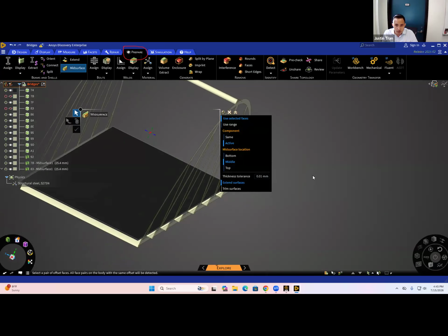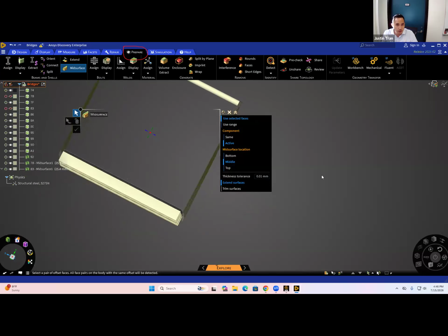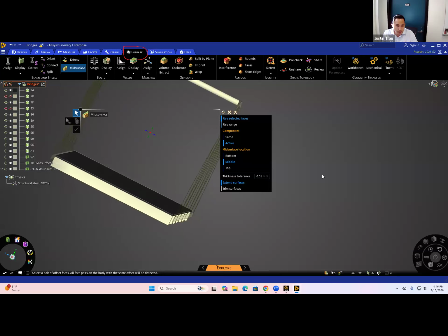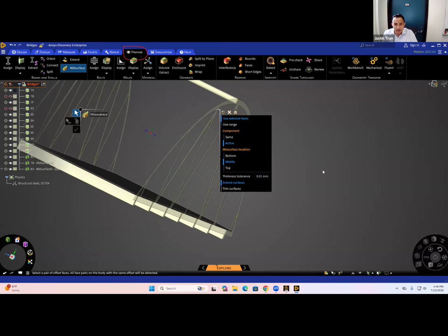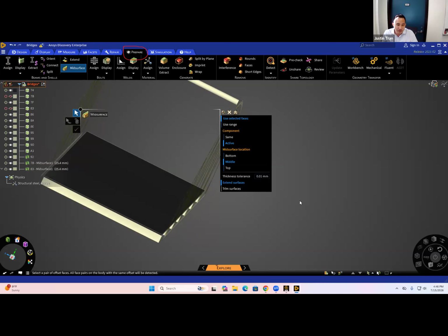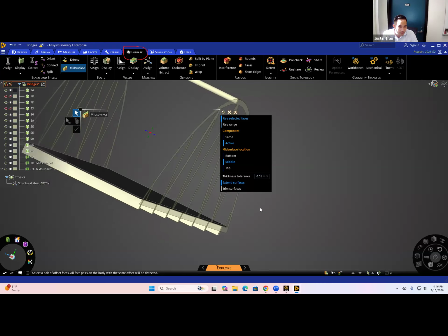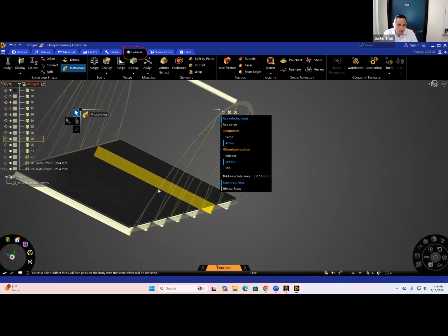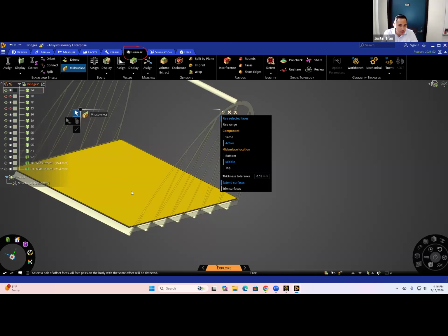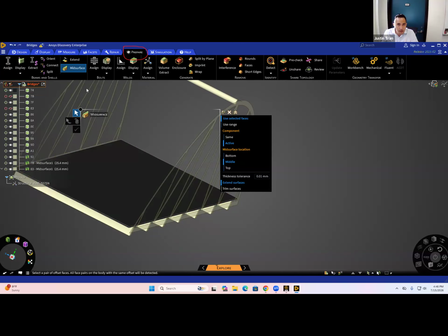And then let's do one for the road as well. This is obviously not a realistic road. If you're making a road for a bridge, you're not making a road of asphalt that's that thin, right? So again, this is not a realistic bridge, but it's more of an exercise for shells and beams. This road here is essentially, you can think of it as just a very thin metallic plate. So once again, we're going to create a mid surface.